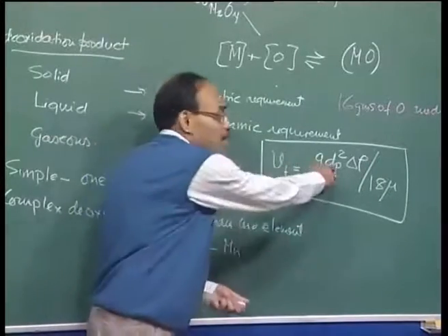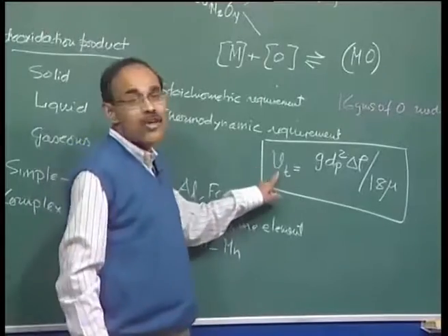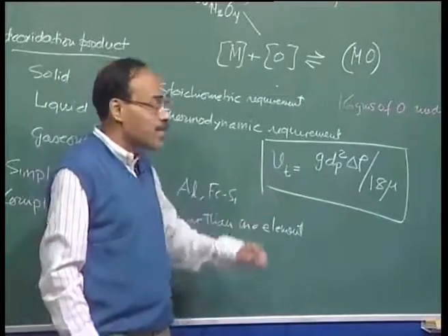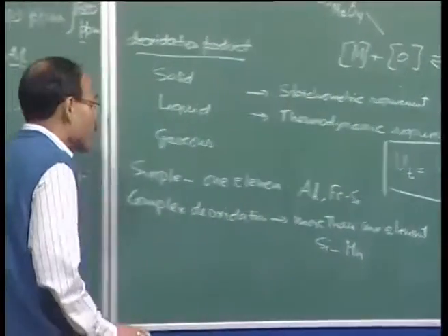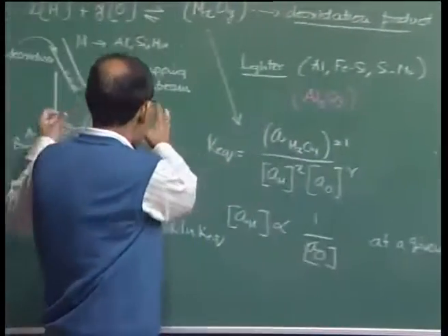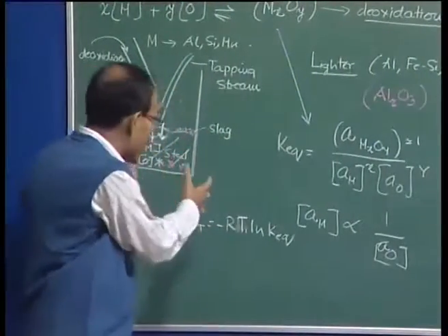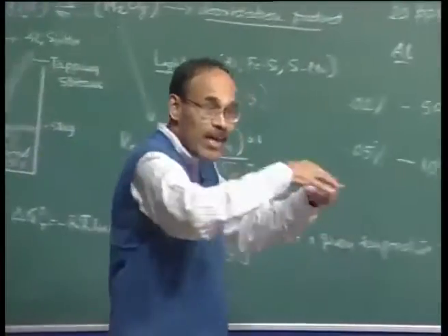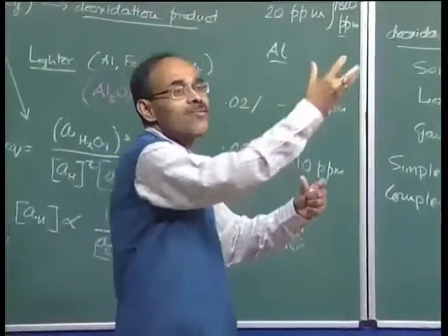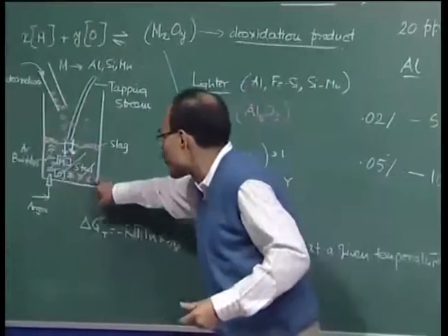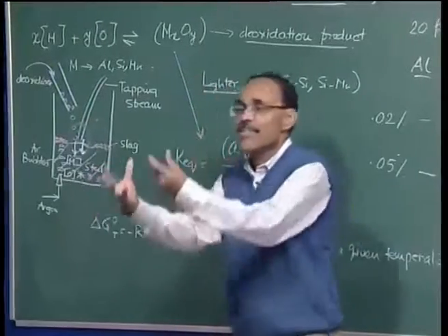If you increase the diameter by a factor of 2, the rise velocity is going to increase by a factor of 4. So, once the ladle is filled up and you are taking it to subsequent stations, you get some time, and in that time the deoxidation products which have formed deep inside the system have a chance to float up.